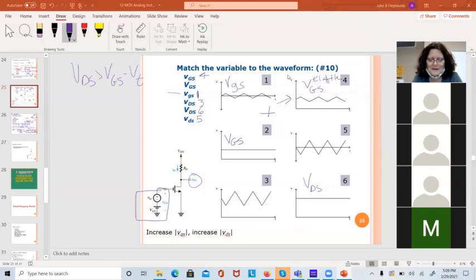Yeah. Mostly electronic devices have ESD protection built into them, but it's usually just diodes. And if some of those are loose, or on one of the keys it got disconnected, an ESD event might be enough to light it up. Interesting. Okay. Eventually it could damage the device, but yeah.